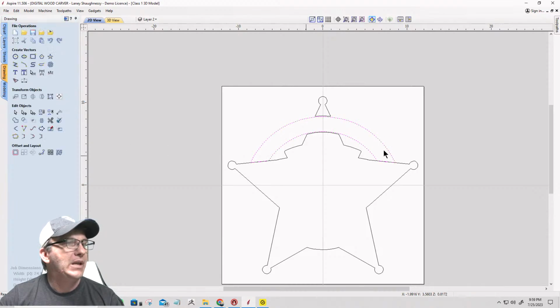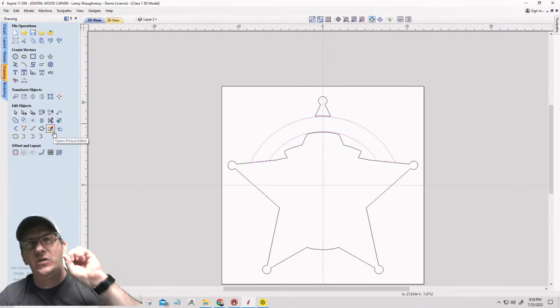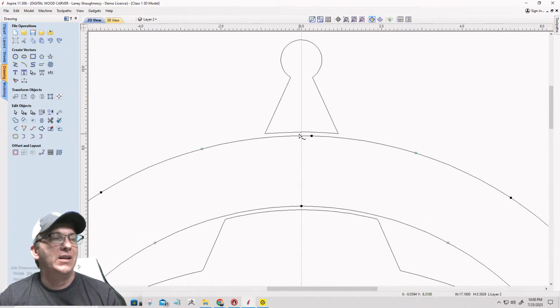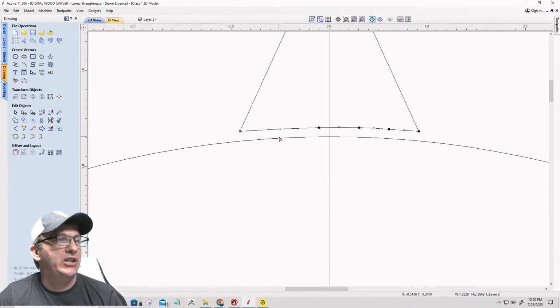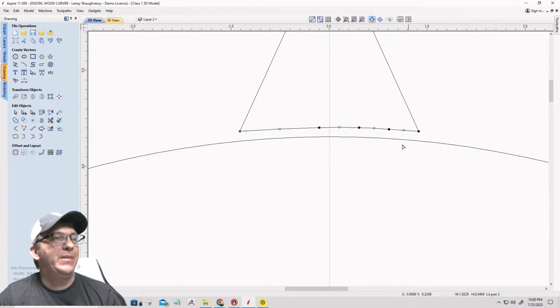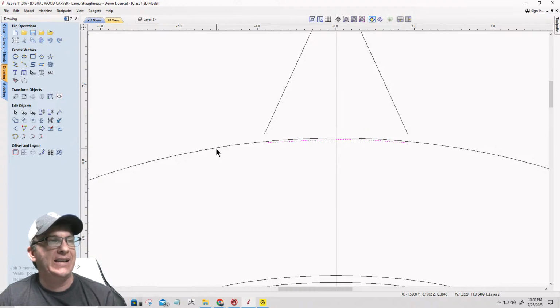All right, so all I did was I clicked on each of these three vectors and used the curve fit tool and recreated them so they're a little bit cleaner with the nodes, because I'm going to be using the nodes for what I'm about to do, and I don't want to have to deal with a million of them, right? All right, so the first thing I'm going to do is cut the vector on these corners. I'm going to take this vector that's selected right here, and move it with the down arrow key, boom, boom, boom, until I get inside of my ring.